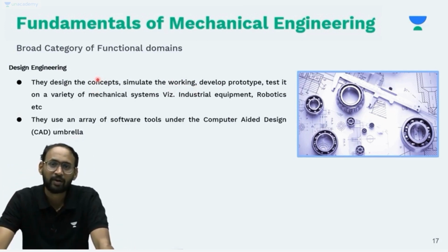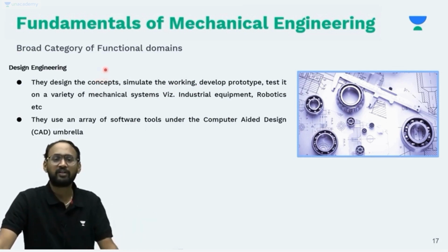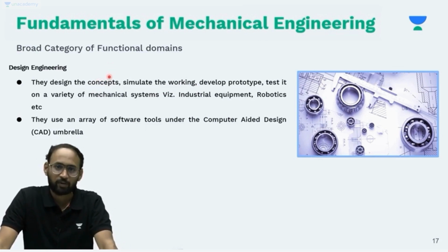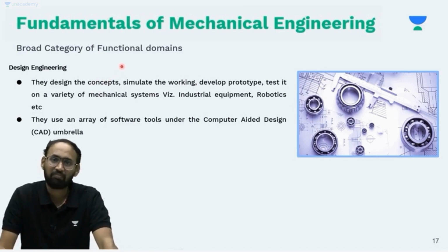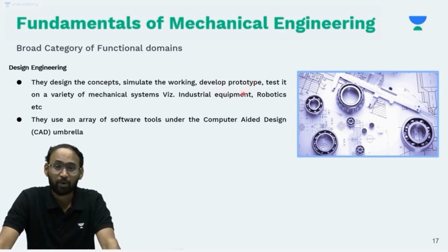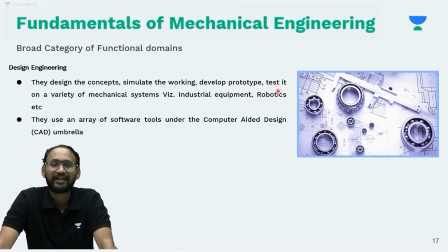So this development drawing is like an engineering drawing where it has a bill of materials, where it has various views. Or it could also be CAD drawings for that matter, or it could be 3D models. And then you develop the prototype. So once you develop the prototype, you have to ensure the functionality is met by doing testing.